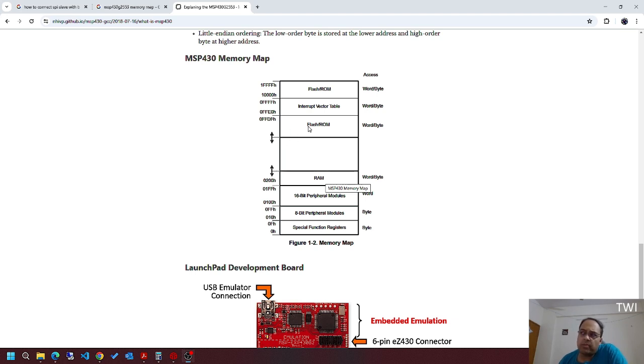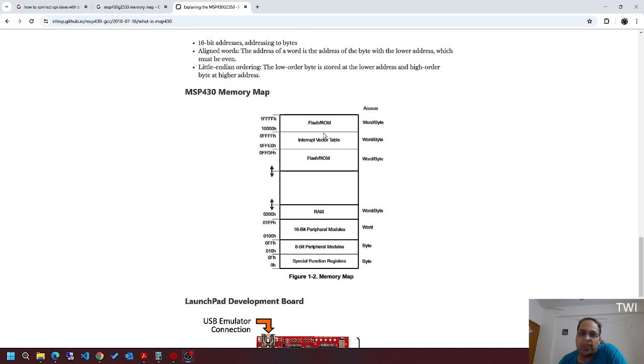So now we will be concentrating majorly on the flash area, because we want a program that can reside inside the flash, and we can invoke it using some method once we detect that a new version is available. That program from that area of the flash should be able to rewrite the original code that was present in your MCU. That is the main target.